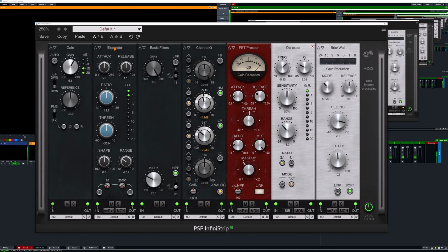Different ways you can go about that noise reduction. You can gate it with a noise gate. Those are kind of hard and kind of abrupt unless you set them really carefully. I much prefer the expander when it comes to noise reduction because it's like a soft gate. You can actually kind of set the ratio at which those very quiet sounds are going to be de-emphasized. And expanders are great. Again, hard to find on just any plugin.